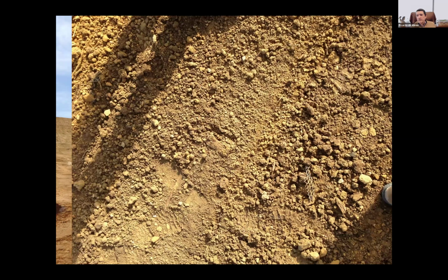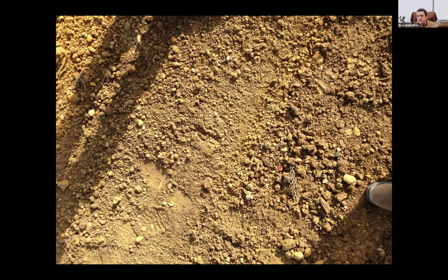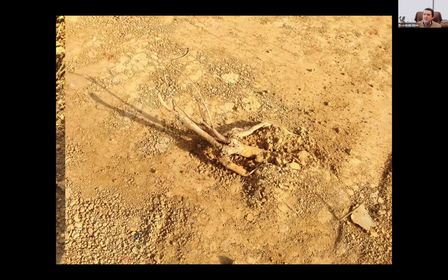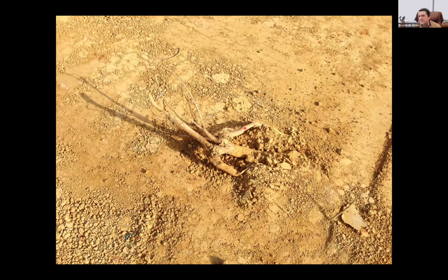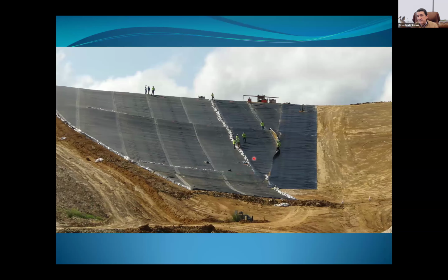One thing is we have to have a very smooth area. So things like this, remove all debris, or like this where you have roots there. All these types of debris have to be removed first before you install the turf itself or install the system itself.